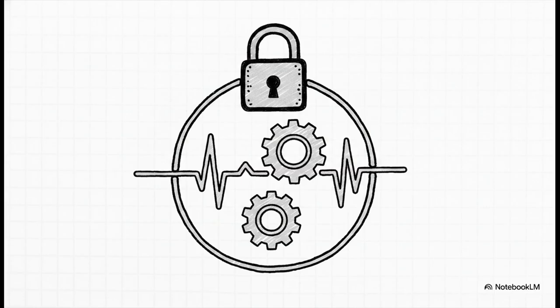The answer is just beautiful in its simplicity. The phase is locked, tightly. It's like interlocking gears. Because every single foreground command, including the control flow, costs a whole integer number of prescaler units, any loop you build out of these commands will have a total length that is an exact multiple of the prescaler period.